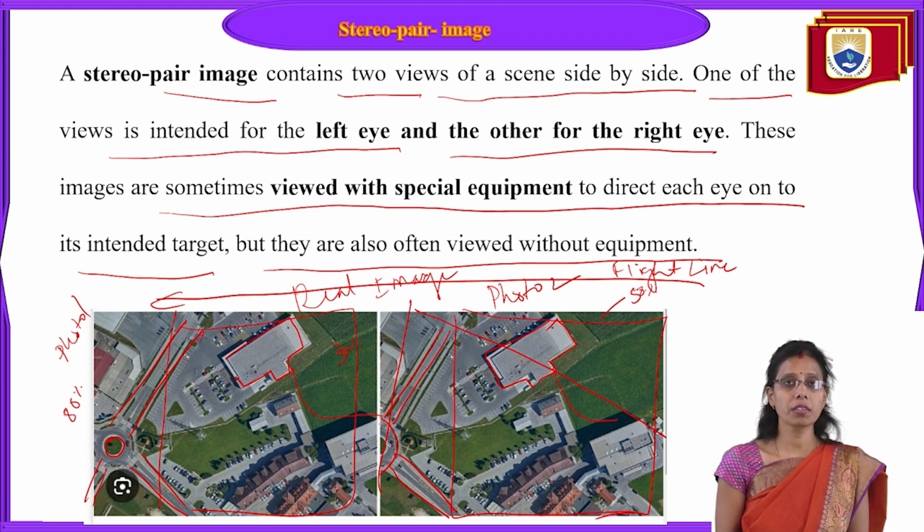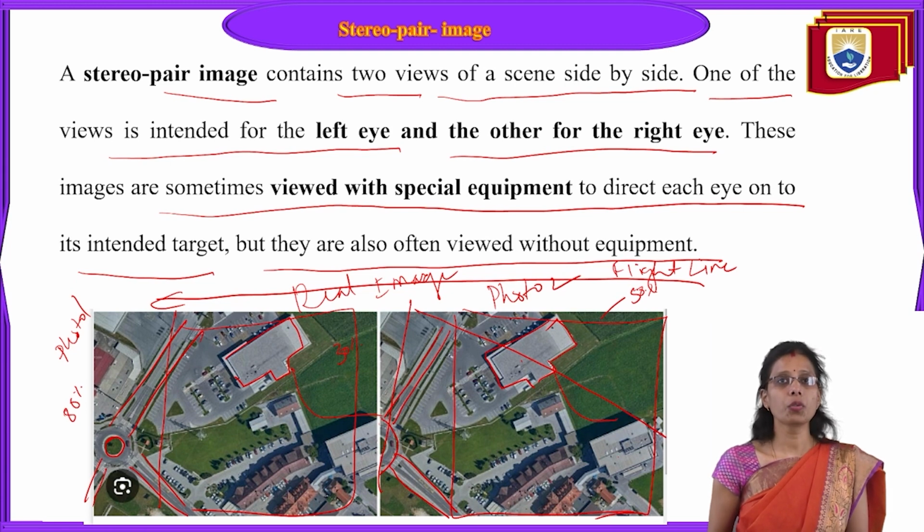It will show you the elevations. This is called stereoscopy. The stereo illusion is seen with the help of one pair of stereo photos, and one pair of stereo photos should be from the same flight line. It should be ensured that the overlap area is more than 60%, 70% to 80%. If this overlap area is there, then only are we able to see the stereo vision.